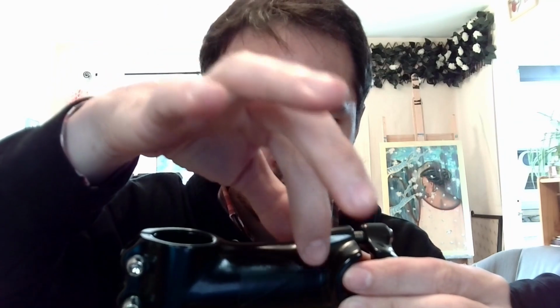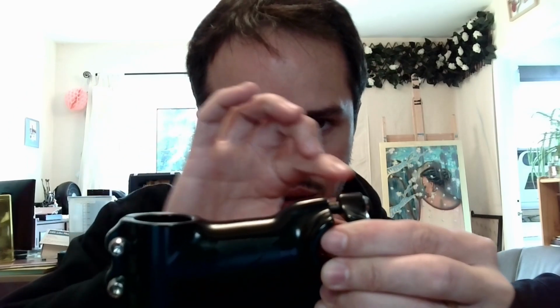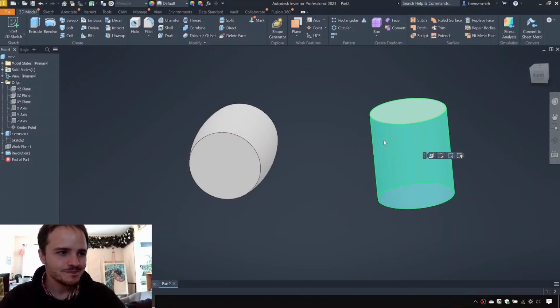What we're going to be doing next is creating the geometry that will connect these two and also allow these bolts to come in. So we'll first create a loft that will connect the center of this shaft to the center of that shaft in a gradual transition. Now, we'll take some rough measurements, but we'll have some artistic license when it comes to this thing. So let's get to it.